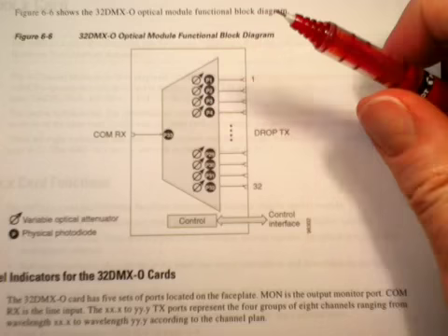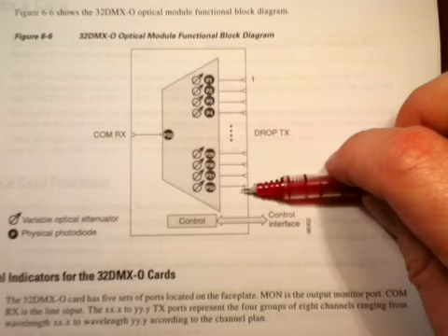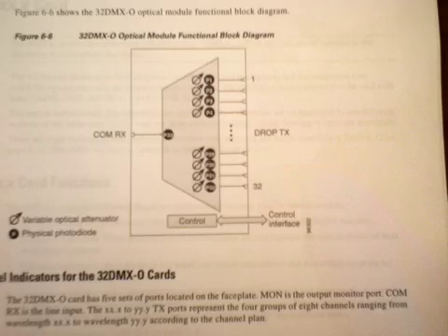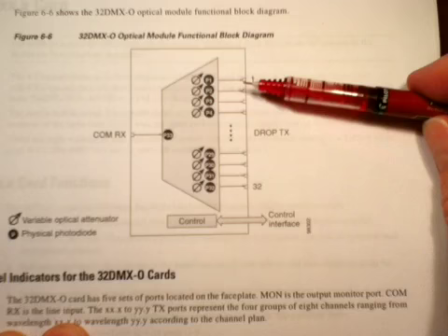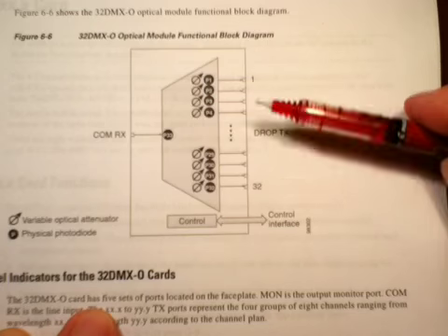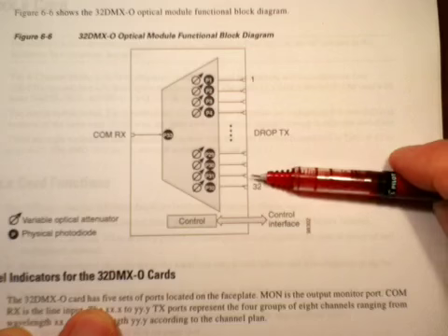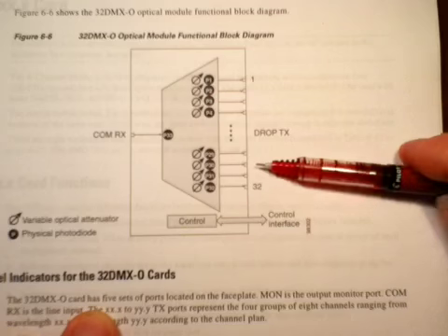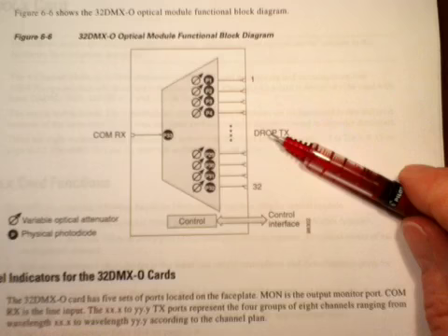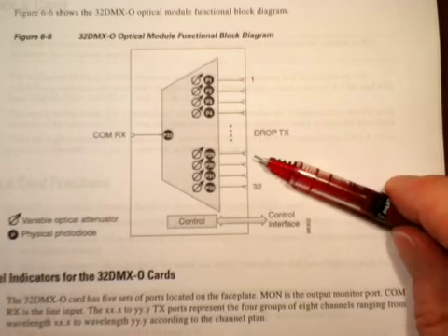What we want is for all of these channels to have the same power in a DWDM system. As I mentioned before, sometimes you have all of your channels turned up, but usually you only have some fraction of them turned up. And the more channels you turn up, the less power there is for each channel. So you definitely want all of this functionality in the MUX and DMUX units.